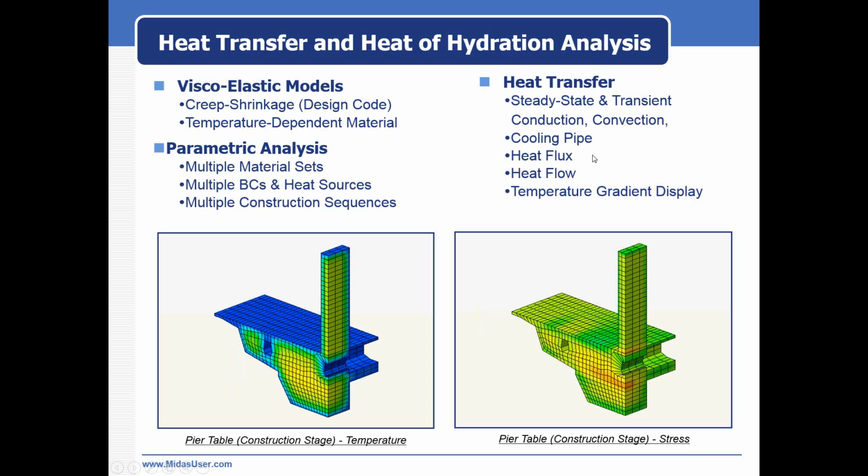Heat of hydration analysis, you must be thinking that it's supported in Civil as well. But the thing is, in Civil, we can model the solid elements, but reinforcement cannot be defined in solid elements. And as bridge engineers, you know that sometimes it's very necessary for mass concreting structures to define the reinforcement and then perform heat of hydration analysis, just like a pier cap.